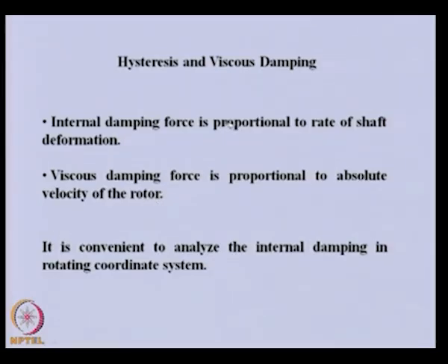And because the direction of this internal damping changes along with the shaft rotation, it is convenient to analyze the internal damping in a rotating coordinate system.